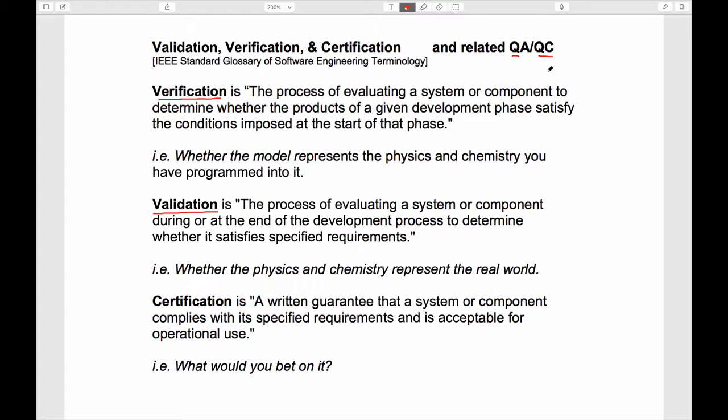And then of course you might wonder whether something's going to happen in the system outside modeling, which is what most people think of in terms of how you verify waste repositories. You put the stuff in, you seal it up, it heats up, you get thermal stresses, those give you changes in permeability, you boil off the fluids, etc. And once you allow that process to take its full place, then you can say something about how many canisters would break open and what the output would be from those canisters and what the impact might be at some compliance location 30 kilometers downstream in the groundwater aquifers, and that's fine.